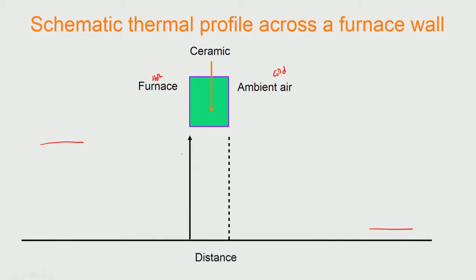So, these curves should come in, and what we know is that the temperature of the wall of the furnace is not the same as the temperature of the furnace. So, if you look at the peak temperature, if it is here, the wall temperature is somewhat here, and therefore, we should draw it like that. Okay. So, Ts, the surface temperature, would be something like that, and we asymptotically take it to the peak temperature in the furnace. Okay. And this difference, Tp minus Ts, is what is actually driving the heat flux into the inner wall of the furnace, and outside also the same thing.